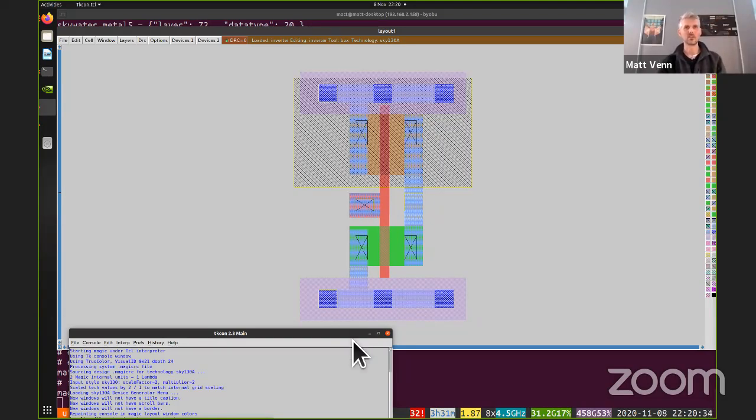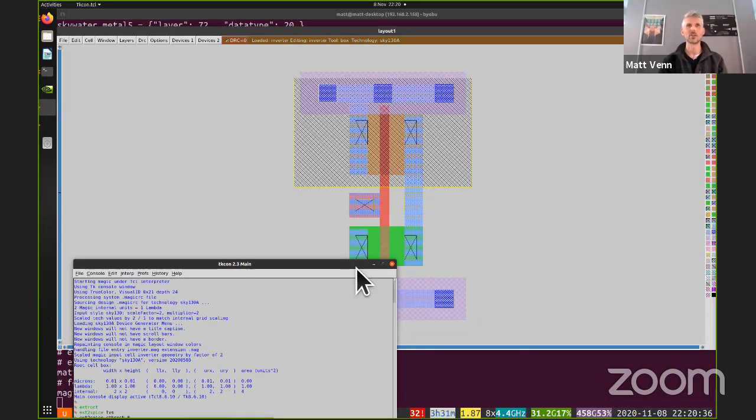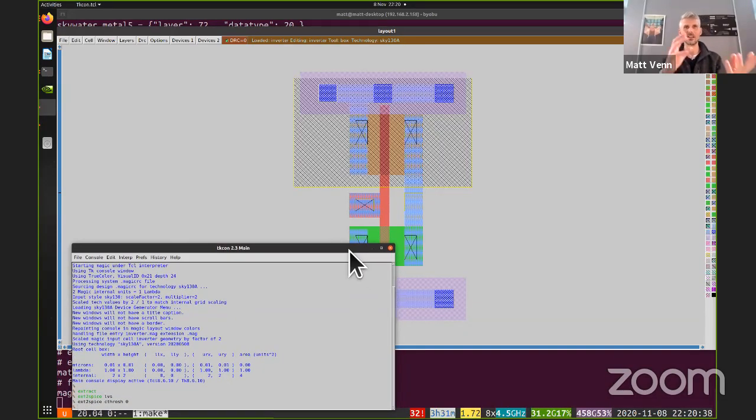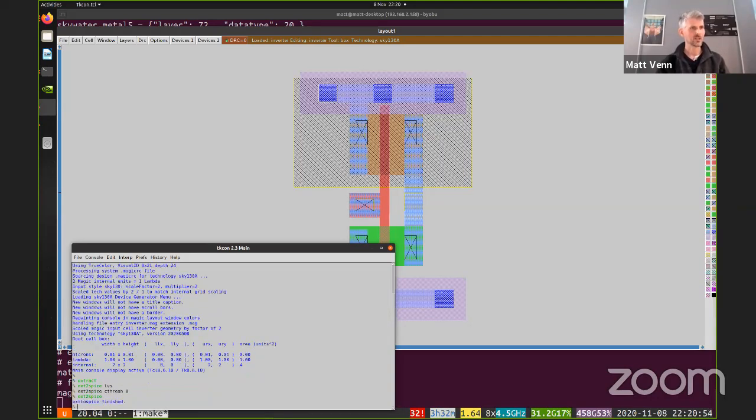And that means that things aren't quite so fast, so they take a bit of energy, and that's the downside. And with electronic engineering, often these things are called parasitic. So we have parasitic capacitance. And what I've done here is turn on parasitic capacitance modeling in Magic. And then when I finally do ext2spice, it extracts all that out into a Spice file.